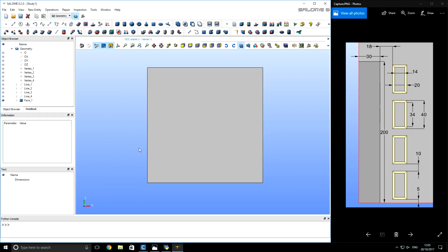Next step, we want to create a geometry for the billet. In reality, our billet is 400 mm long, but since our problem is symmetric, here at the bottom you can see the symmetry plane, then we can simulate only half of the billet, which is going to be 200 mm long, and 30 mm in radius, so that we also do not simulate a half of the domain here, which is axial symmetric against this axial line here.